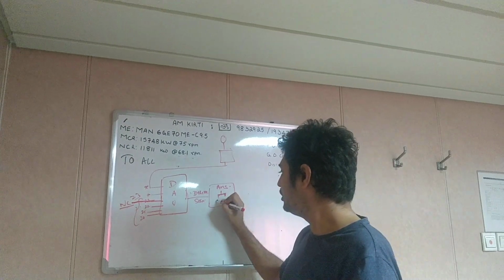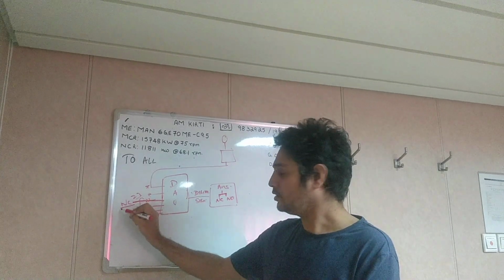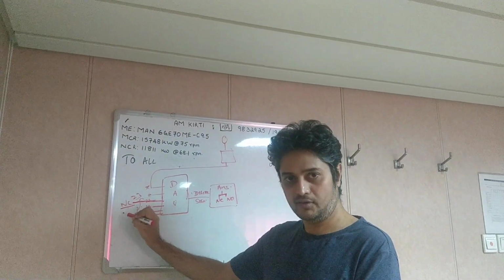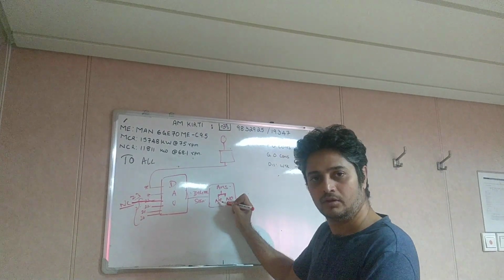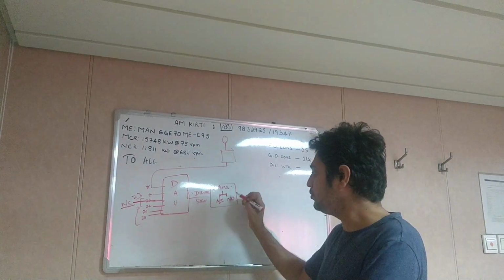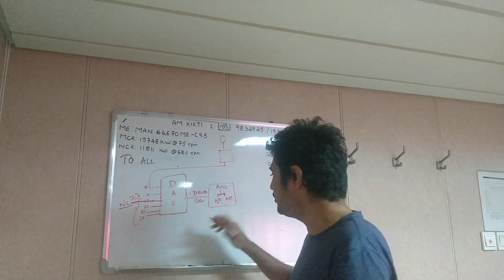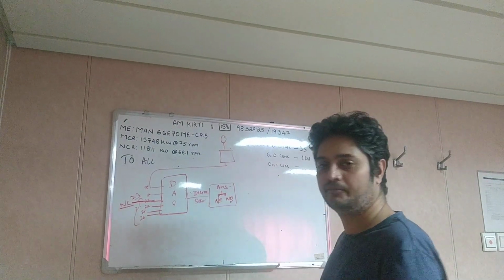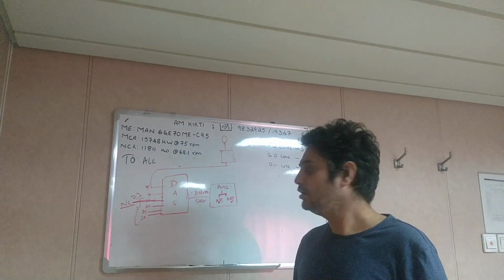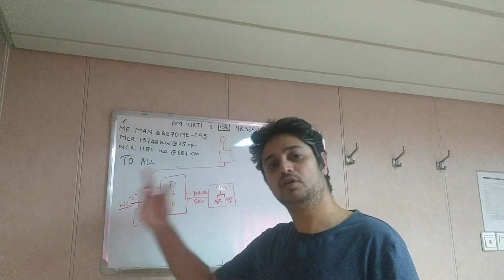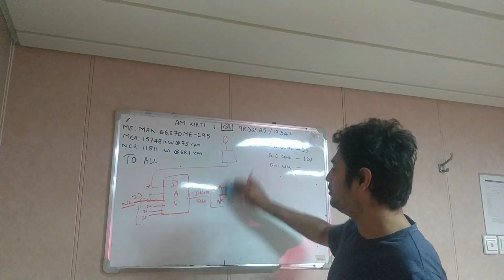So there you can see NC, NO. If it is NC as per the circuit, here also it would have been set as NC. That means when it becomes NO, only then the alarm will come. Correct? So sometimes what electricians do is they uncheck this and check this. That is also a way of inhibiting. By doing like this, what he is trying to tell is, when the circuit becomes NC, then you trigger an alarm, not during NO. Understood?